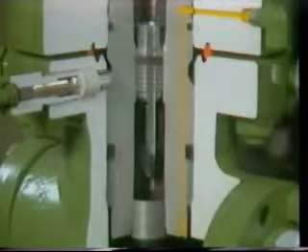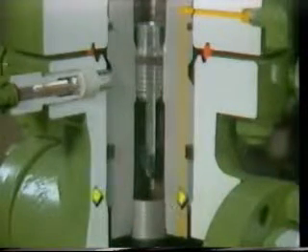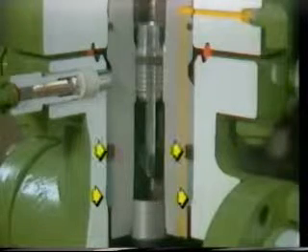Whether onshore or offshore, a tubing head is installed next, after the last casing string has been set and the well has been or will be completed. The tubing head design and function are very similar to that of the casing spool. The top bowl of the tubing head provides a load shoulder to support the tubing hanger and packoffs.